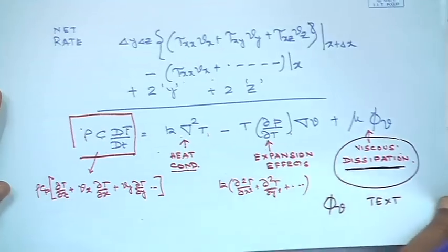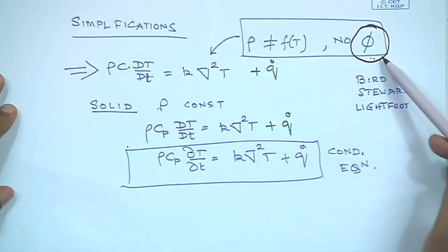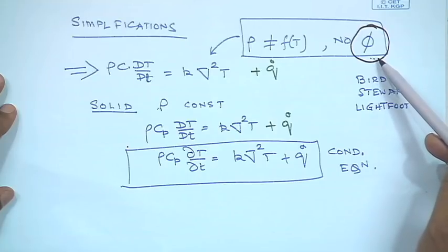So, a simplification of this equation, which I have shown before, results in the following equation, where the phi, which is the viscous heat generation, is usually small unless it is a special situation like high speed flow through a narrow conduit, or a very high viscous fluid flowing with a high velocity.